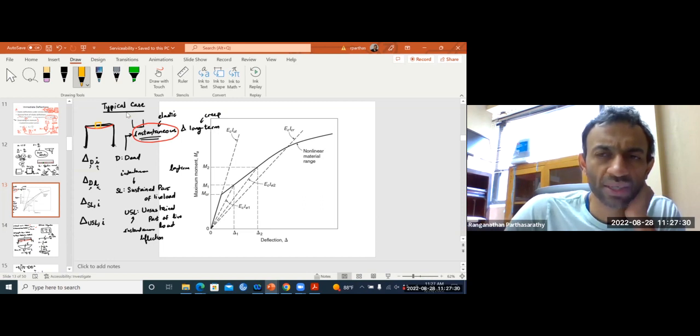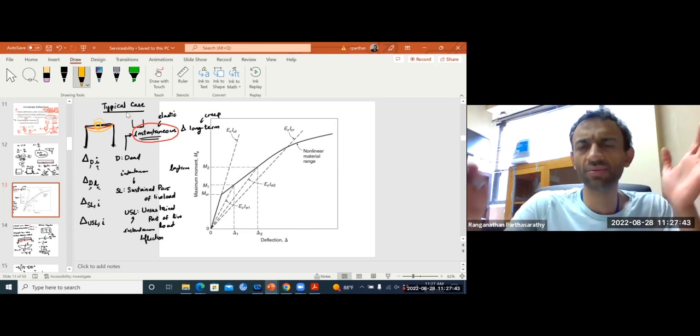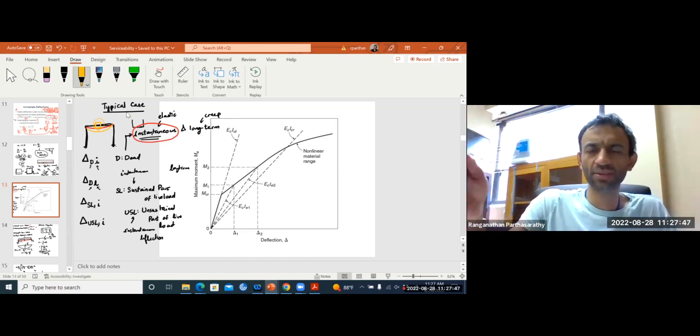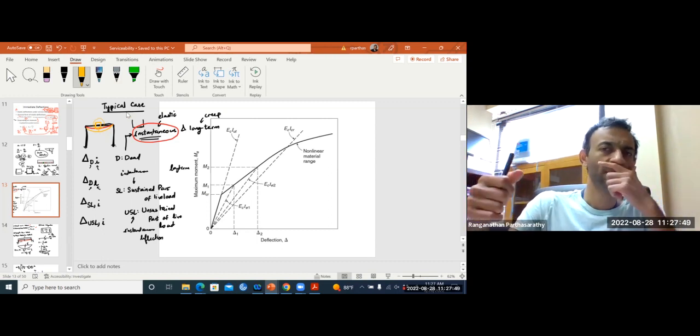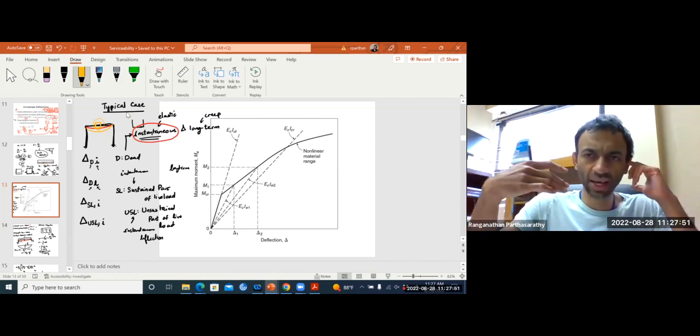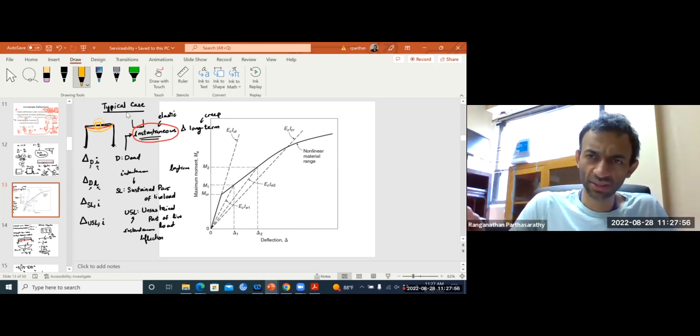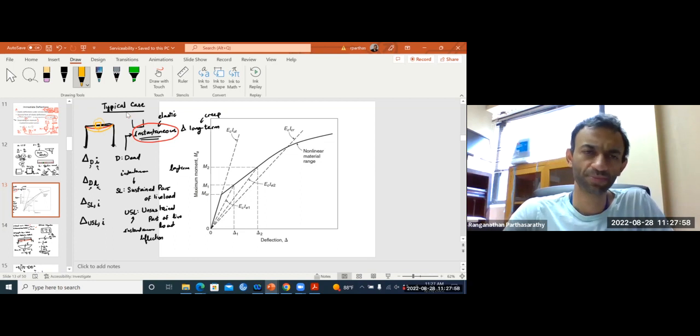So once that equipment came in, there will be more deflection. That is what is important for your equipment. So in the presence of your equipment, there was some additional deflection that will determine what is happening after you place your equipment. Okay, when it first comes in, that doesn't matter. So what happens after that will determine whether your deflection is within the tolerance or not.